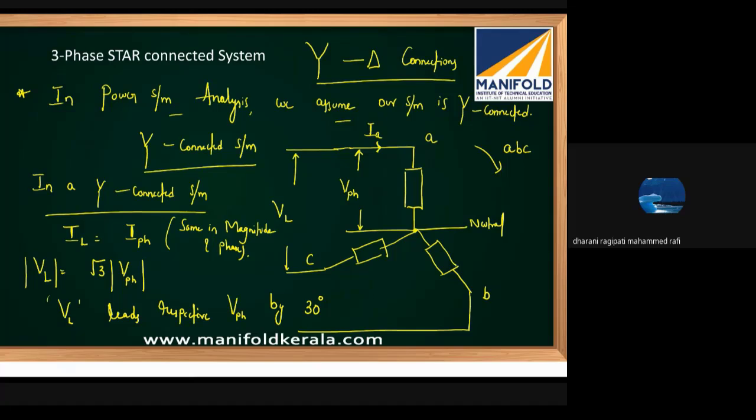Always remember the impedance that is connected between phase to neutral. This is called Z phase or ZL per phase, whatever. The impedance that is connected between the one line conductor and the neutral is the phase impedance. There is no concept of line to line impedance. Impedances are always treated as per phase impedance only.